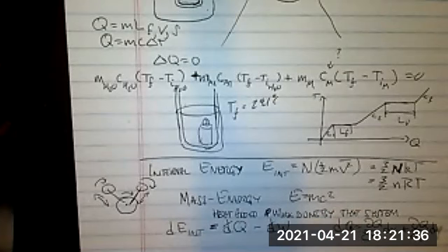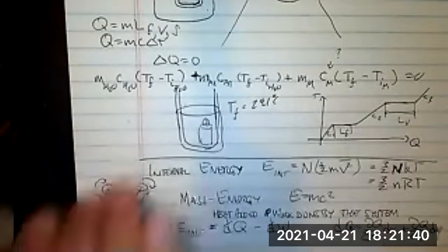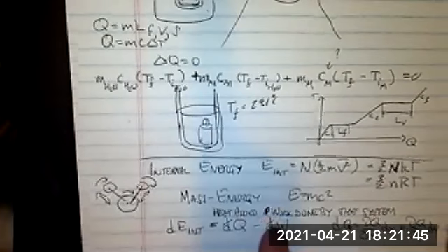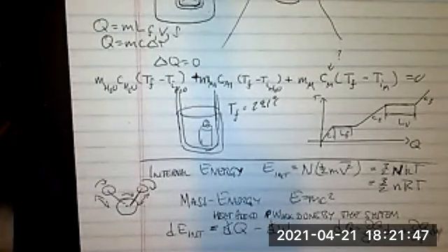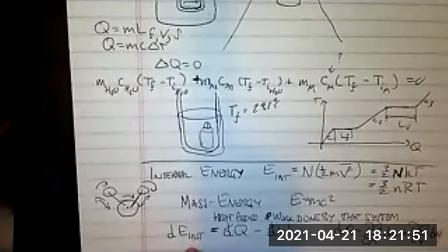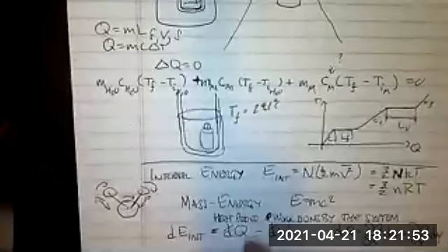And because the pressure increases, that's going to push the cylinder lid up a little bit and, in fact, do work. Well, that work that's done takes away from some of the internal energy that could have been increased. So that's why we put the minus.